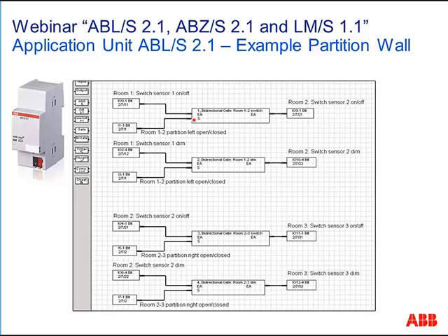And now when our separation wall is closed, this telegram comes from our sensor number 1, stops here, but when our separation wall is open, it is forwarded or converted into this group address and now controls the dim actuator in the second room. And the same works also vice versa in both directions. This is, I think, the easiest way. One gate for switching, one for dimming.